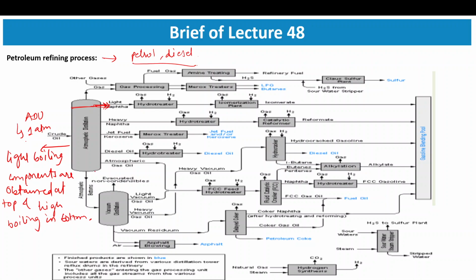Right, there will be similar cuts provided near the trays, and it depends on the boiling points of the different cuts that you want. So these are the basic products. You can have very light boiling gases like methane, ethane, and some other organic compounds. Then, as the molecular mass increases, the boiling point increases, and you will have gasoline, then heavy naphtha.